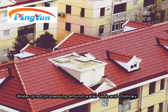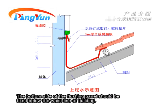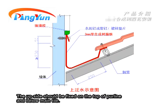Waterproof processing around water tank and chimney. Flushing panel around water tank and chimney can be made by metal sheet and synthetic resin sheet. The bottom side of the flushing panel should be fixed below the waistline of the building. The upside should be fixed on the top of purlin and below main tile.